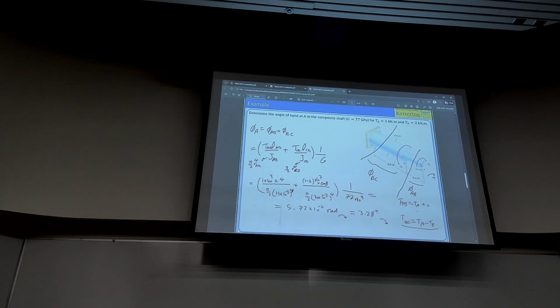Now let's talk about this. Again, we want to look at the effects of these two loads on the segment. If I apply this torque, would it cause any deformation in BC? That's why we superposed the two. We subtracted the two just because the two are in reverse direction. You see that?